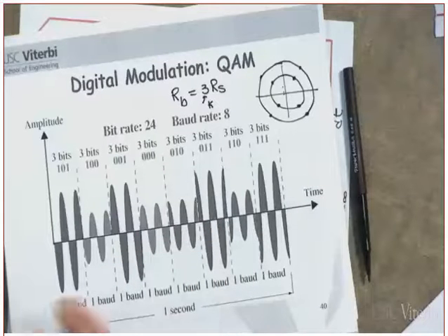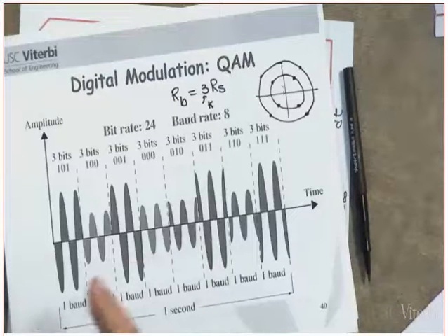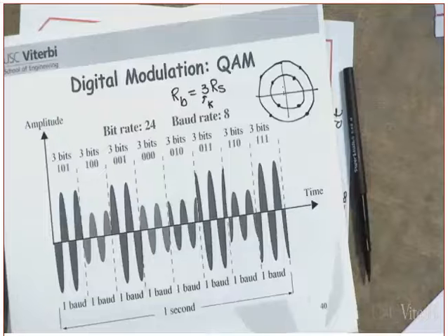We will see later on that these are more bandwidth efficient than constant envelope modulation, like the GMSK or the MSK. However, this one would require the power amplifier to operate in the linear region. Are you following or not?